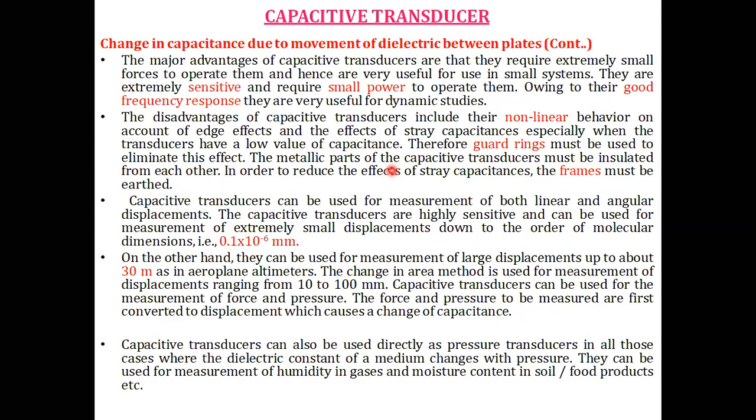Guard rings must be used to eliminate this effect. The metallic parts of the capacitor transducer must be insulated from each other in order to reduce the effects of stray capacitances. The frames must be earthed.